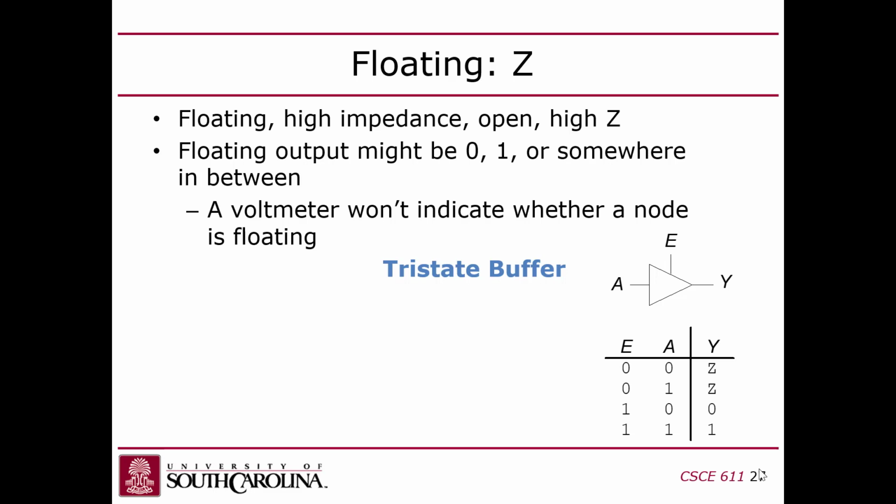When I say VDD, I'm talking about whatever voltage you're operating your chip at. Generally speaking, these days on most modern chips, it's 1 volt. So, 1 volt means true, something close to 0 volts means false or 0. If something is floating, though, it's not connected to anything. So it's like an open circuit, basically. If you connect a voltmeter to it, it would give you some value between 0 and 1 volts, right? Although you don't know for sure by measuring the voltage if it's floating.